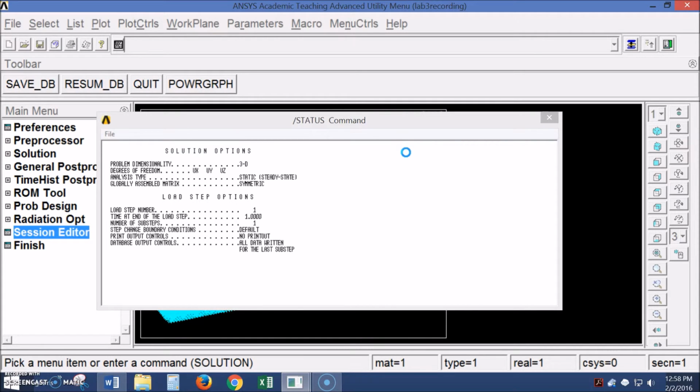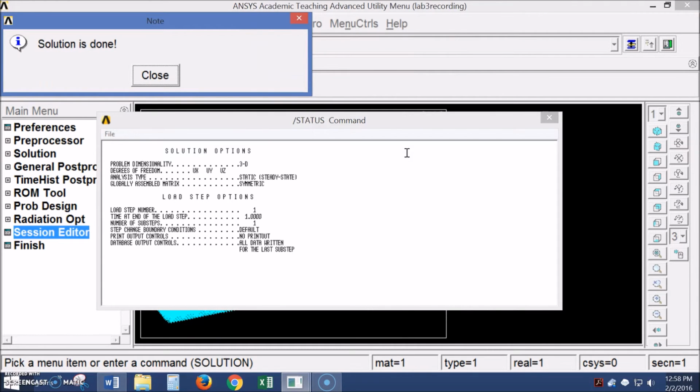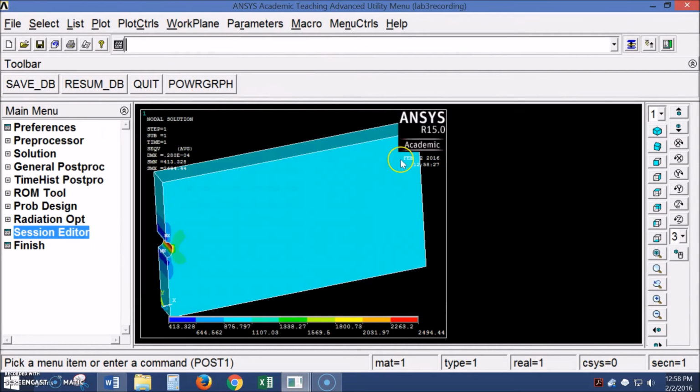And now if you wait for it to solve, it'll replot for us, and we can see that our stress is smaller. That may seem confusing at first, because you would believe that with a smaller circle, it's a smaller radius, and therefore the stress concentration should be larger. And it is, but you'll see once you calculate that, because this area right here is a lot larger, that smaller number actually makes sense. Anyway, when you do the math, you will get a larger KT value.